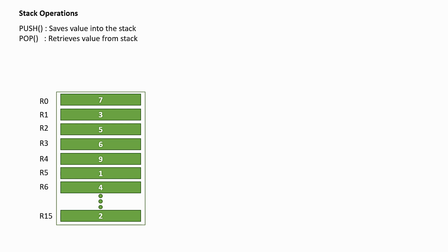the stack. As I said, stack is a last in first out storage region, so you can only pop out the last stored value. You cannot pop out a value stored before the last one out of the stack. And let's consider these are all the basic registers available in the microcontroller, that is the ARM Cortex-M processor, starting from R0 till R15. And these are all the values inside the registers. R0 we have 7, R1 we have 3, etc.